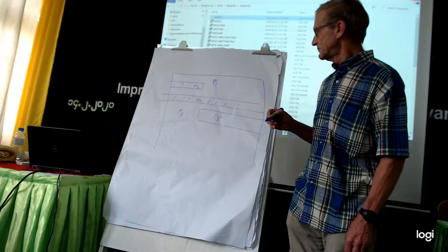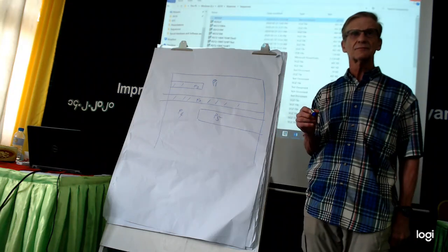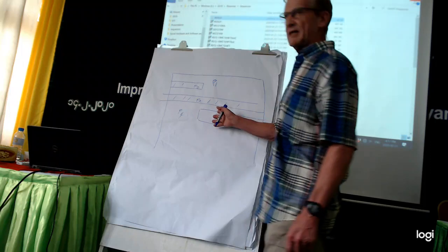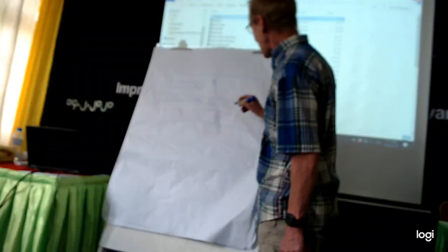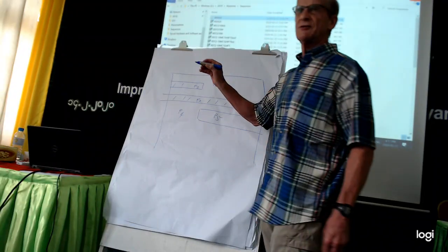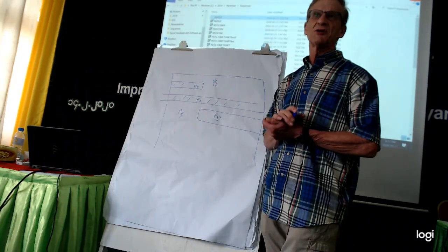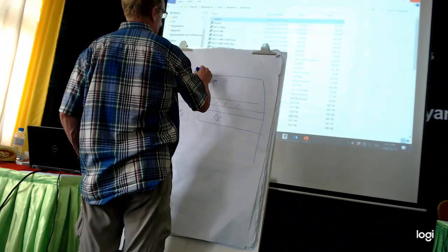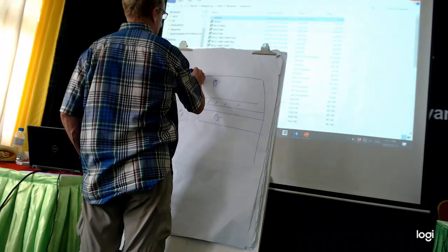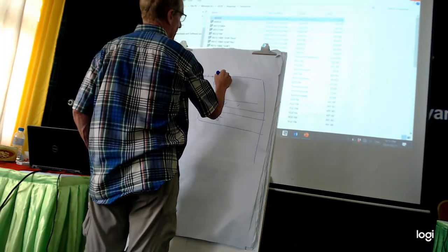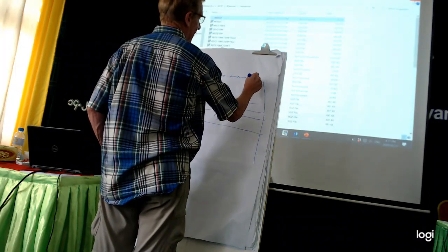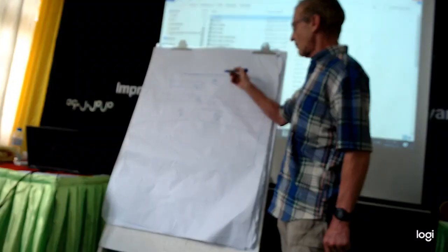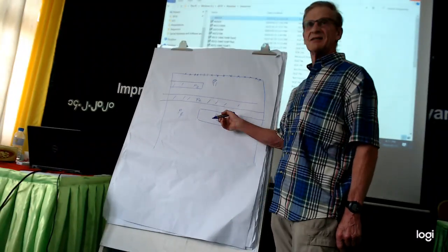So say you're looking for this, and you think let's do a Wenner Schlumberger. So you set up your electrodes on the surface, and then you want to see, okay, can I see deep enough to see this?